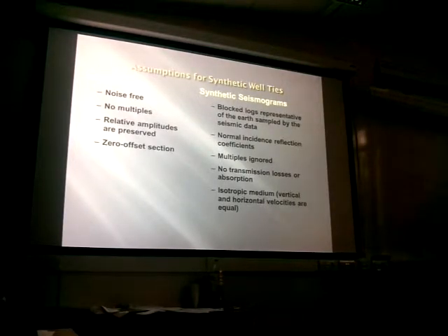So a wave that is far from the source has a lower energy density. For the one very far from the source, you have to take that as an option when you calculate, and set the software to assign the spherical spreading, or the amplitudes are going to disappear. You are also assuming an isotropic medium, and we know that the stratigraphy is not necessarily an isotropic medium.